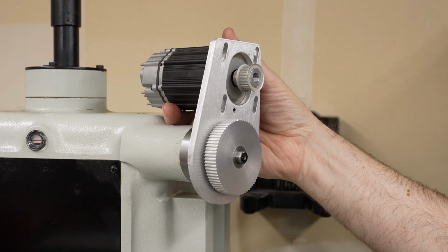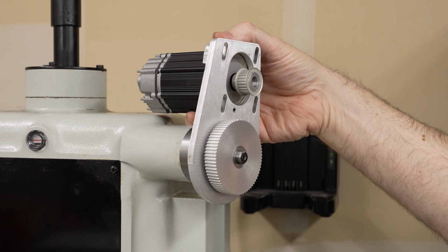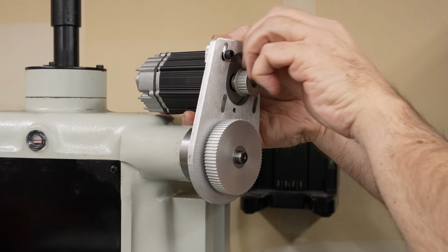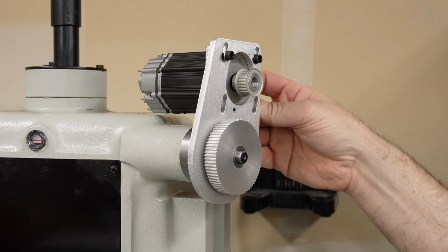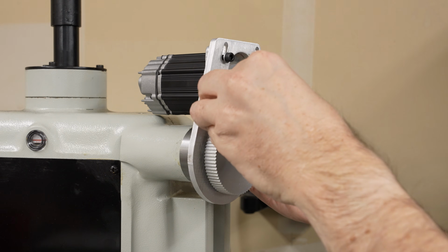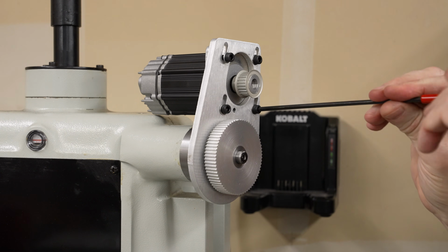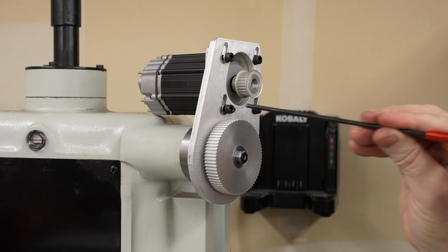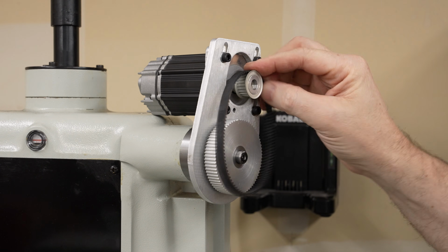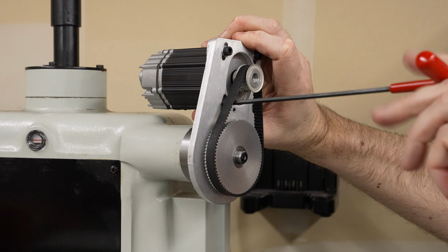Motor goes back on just the same way we put it on multiple times before, with these laser cut nut plates on the back and 4 M5 screws. I'll put these in loose initially with both of these nut plates on here so that the motor can slide up and down in those slots, and that'll give me the freedom to install the belt and adjust it for tension before I tighten everything down. And unlike the Z-axis, we have so much better access here that the belt just goes right over the pulleys with no trouble. I had to fumble with that down on the Z-axis just because there were so many things in the way.